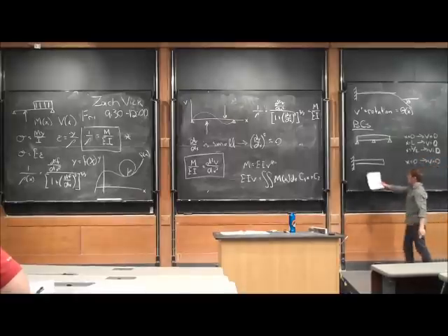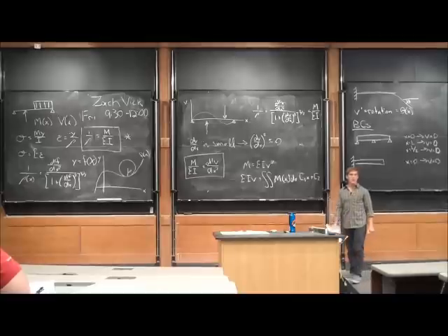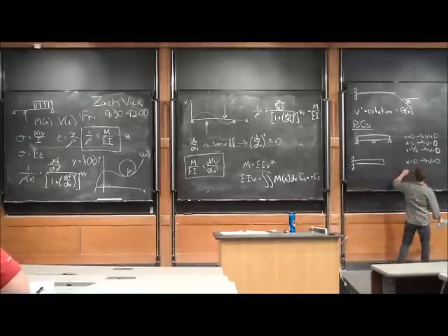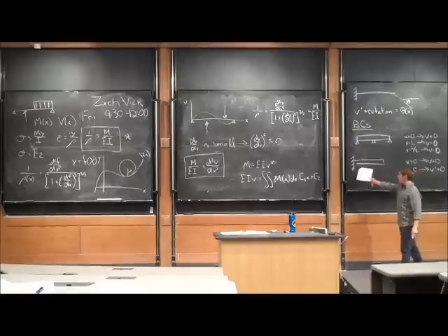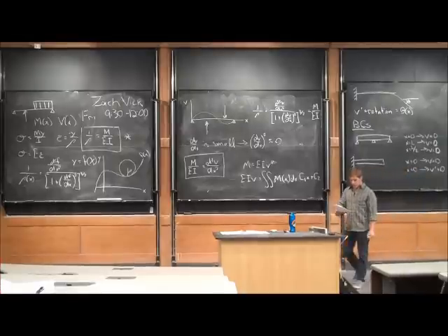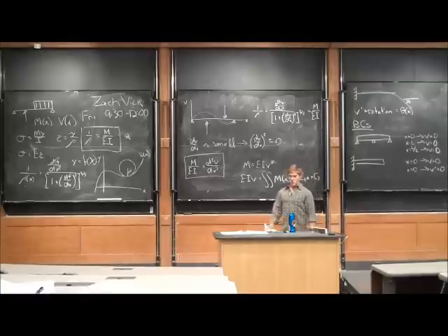Also, at a cantilever beam, you can't rotate where you're connected to the wall. So our other boundary condition in this case is that at x equal to 0, v prime is equal to 0, because v prime is our rotation. We're going to have 0 rotation here at the wall. So those are examples of how you look at boundary conditions.